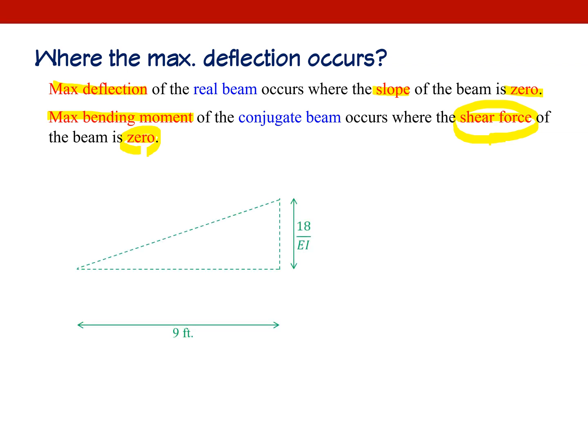Okay, alright. This is my bending moment diagram, the left hand side. And I'm going to assume that the maximum bending moment occurs within the left hand side. If I'm wrong, then when I get the answer, I'm going to check the right hand side. But most probably, the maximum bending moment will occur on the left hand side because it's longer.